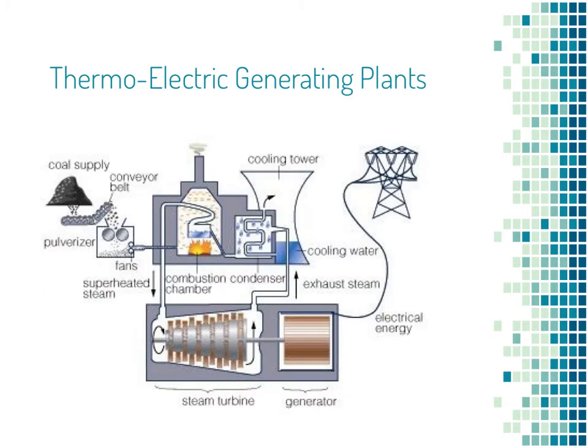So we can see here we have some sort of coal. We burn it. It heats a tank of water. The steam is directed down into piping and turns a steam turbine. The turbine turns the rotor in a generator, and that produces electrical energy. The steam, having turned the turbine, comes out, condenses or cools back down into more water, and can be fed right back into our combustion chamber. So we can keep recycling the water at least, but not the coal.